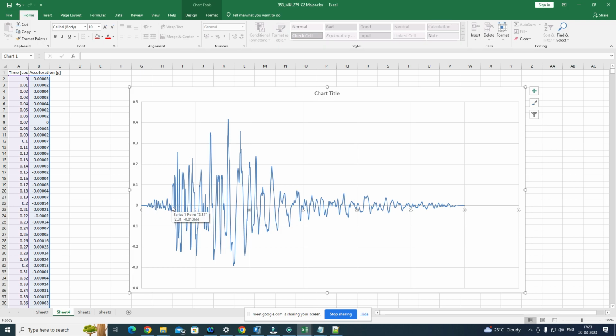So it was not having any significant impact, that's why the analysis was running so fast. But after reaching this point, suddenly this amplitude increased. So it is giving a lot of non-linearity to the structure, and because of this, the analysis pace actually reduced. So this entire range from this to this, somewhere here, will be a little bit slow.